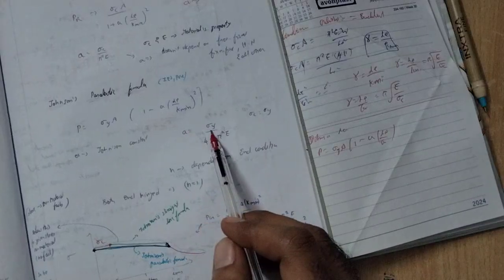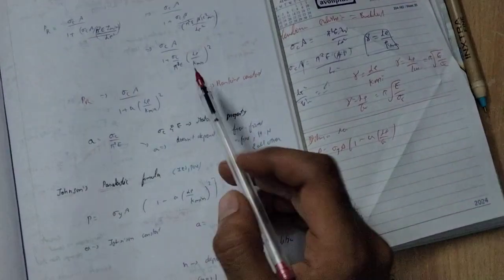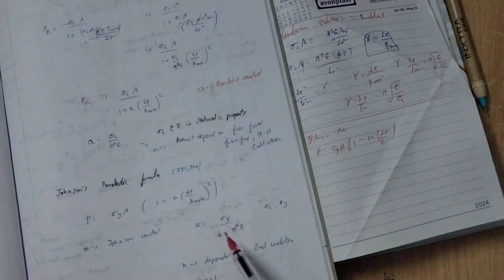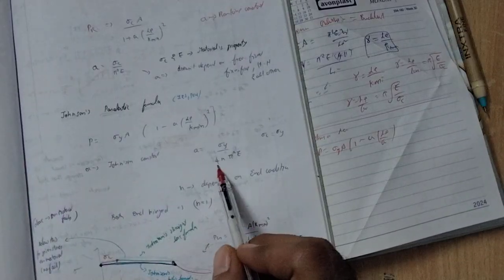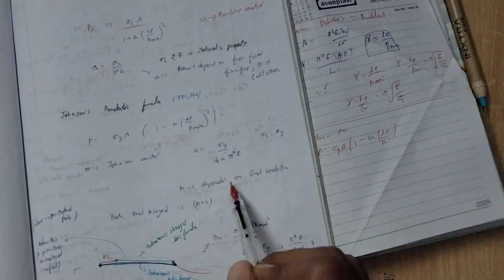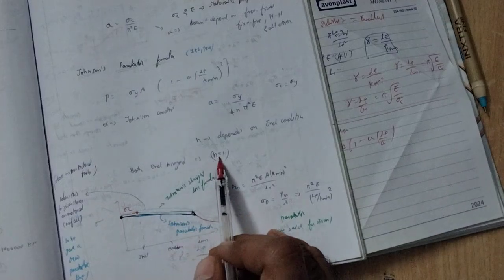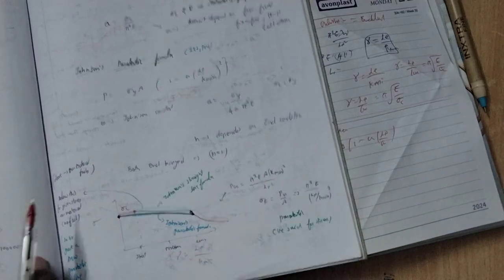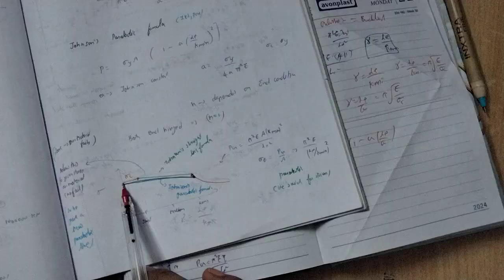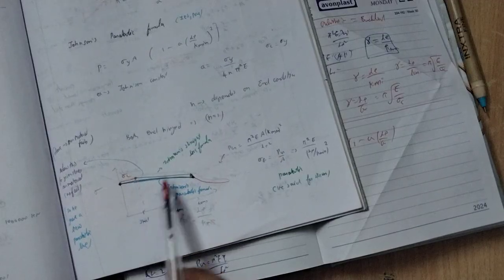So A equal to this entire thing is sigma c pi squared E, but here the n will come. Okay, n depends on the hinge condition. If both ends are hinged, n equal to 1. So we can see in this graph this is the crushing load, and you can see Johnson's straight line formula,